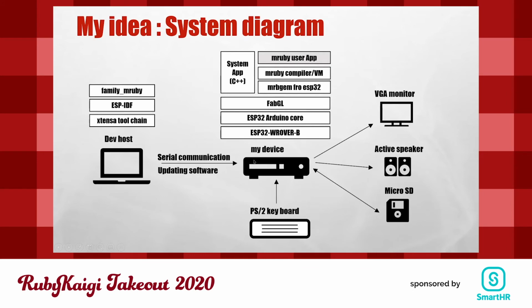For the development phase, I use a development PC. We can make the firmware using the ESP development tool. Compile the firmware, then transfer the software using serial communication. Once the software is written in the device, then we don't need to connect the host PC.